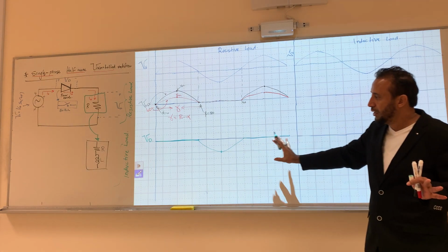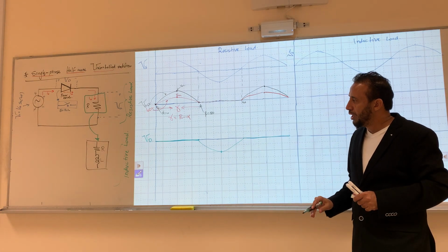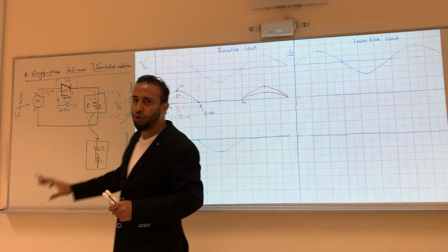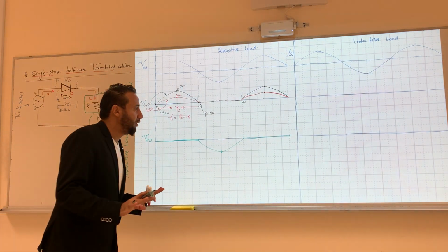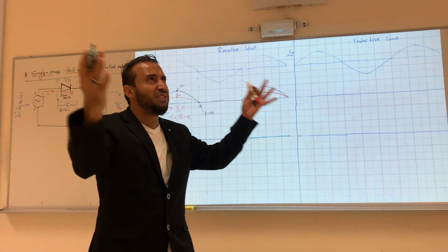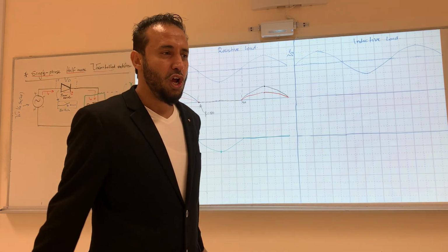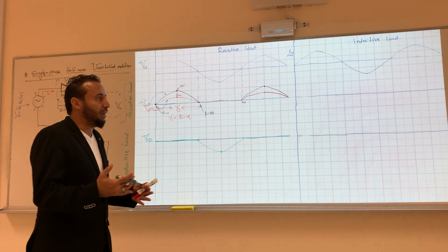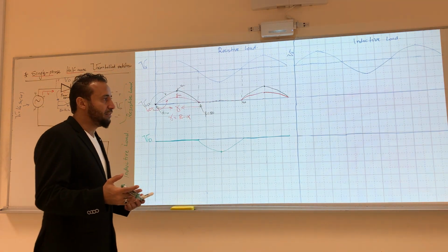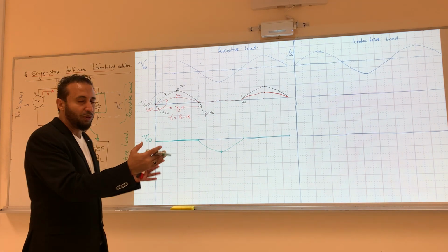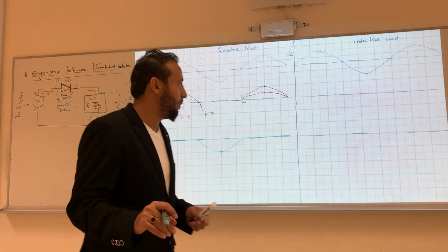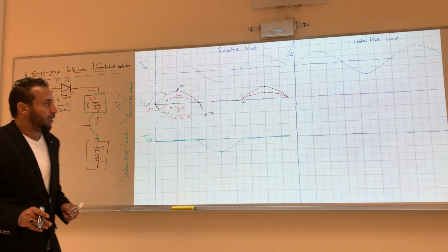That's what you will see when you just add resistive load by itself with no inductive. We know that the resistive load represents lights and similar loads, and the inductive loads mainly represent motors. We will have a small issue when we connect inductive, and we will come to it.